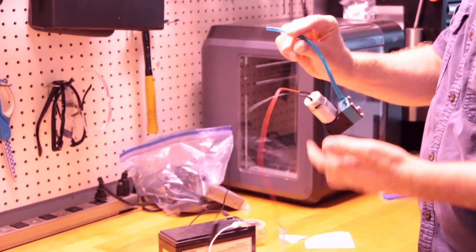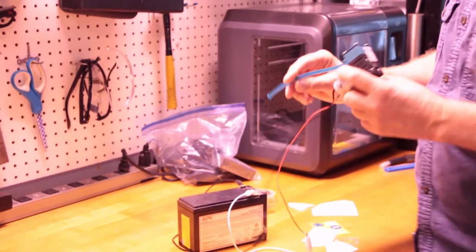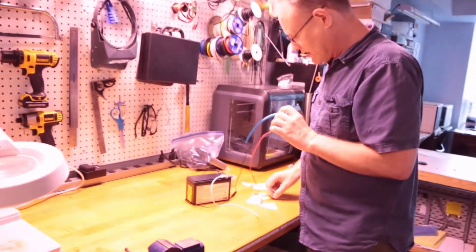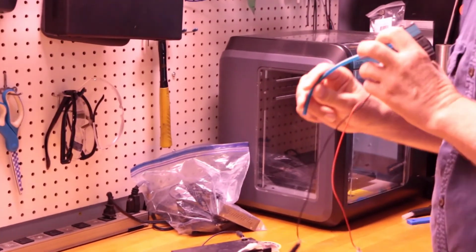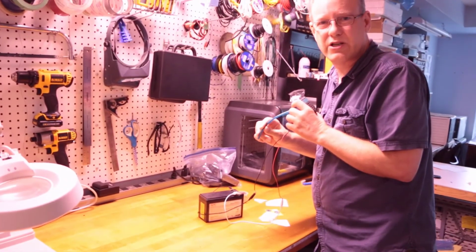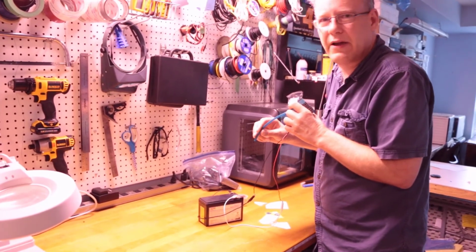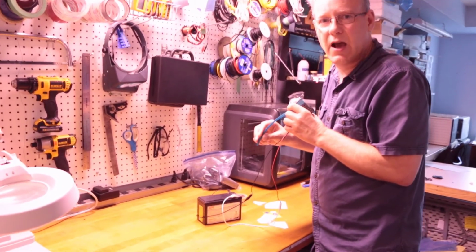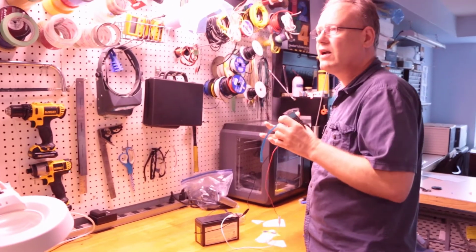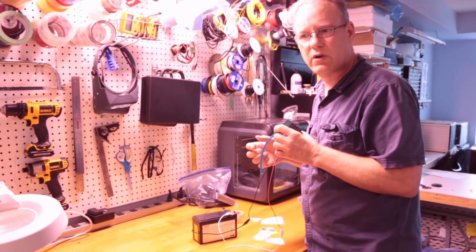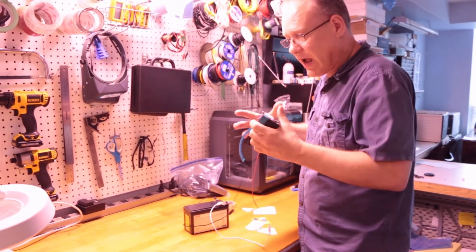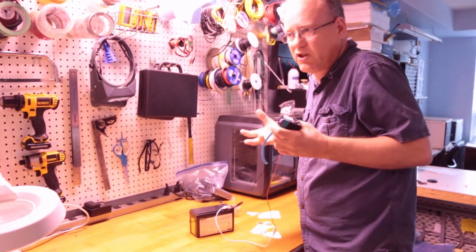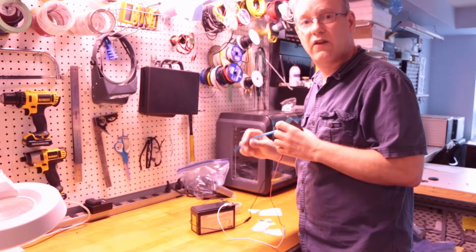Now what I want to do is some work with this thing. One of the things about vacuums is the larger the surface area here, the more work you can do with it, because pressure, force, and area are all connected, and we know that the larger the area with the same pressure, we can create more force. The same exists with vacuum. When we have a greater surface area, we can create a greater force differential.